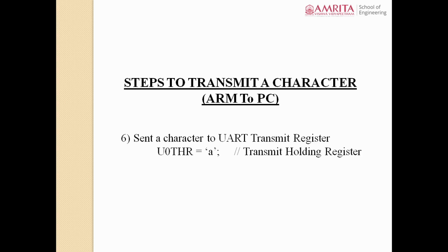UART is ready to receive my next data, right? So in order to identify whether UART is ready to receive my character, you should check whether the shift register is empty or not. Which shift register? The parallel to serial shift register, which is used for transmitting the data.